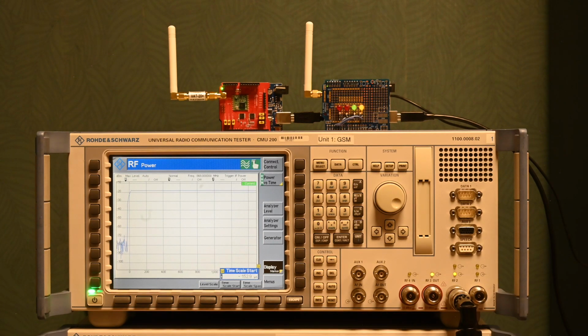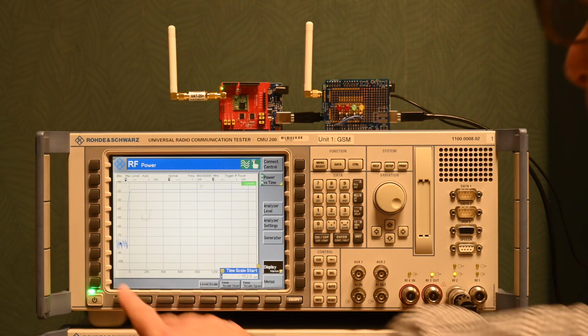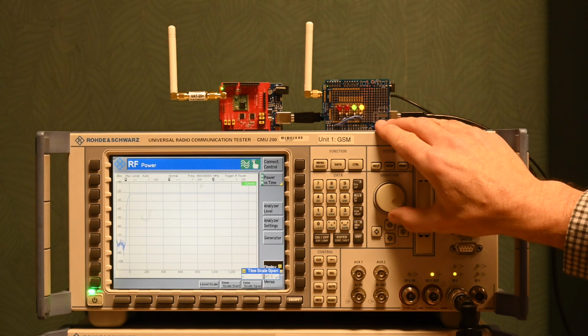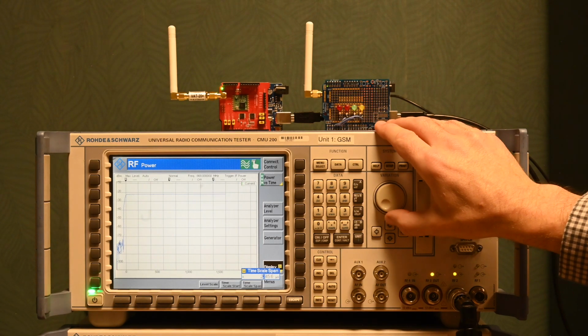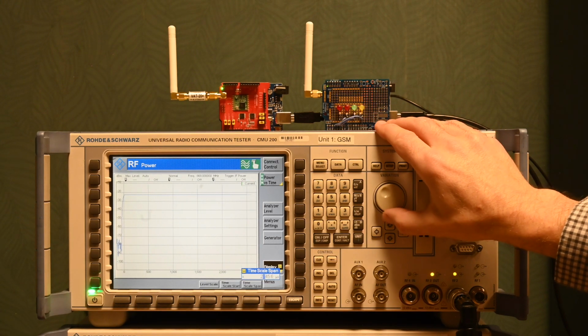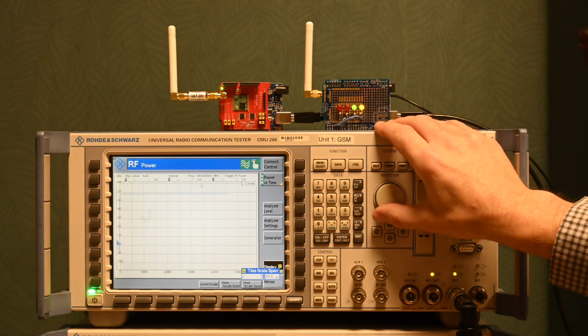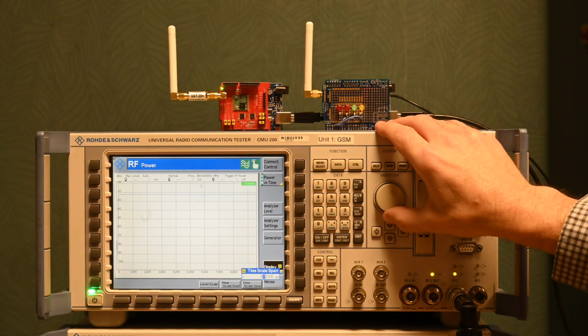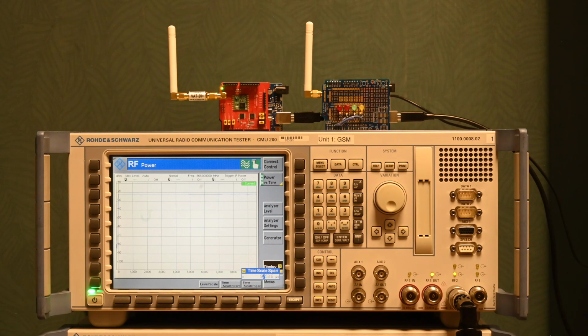So it's a negative value, it means that we see a little bit of the value before the trigger point is coming in. And we got the time span, and that's what we're interested in. And so if we decrease the time span, we can actually see that also happening here with the divisional lines here on the screen. Make it bigger and bigger. And then the thing is that we're at the maximum level here, and we're not getting the complete burst yet. So what is going on?